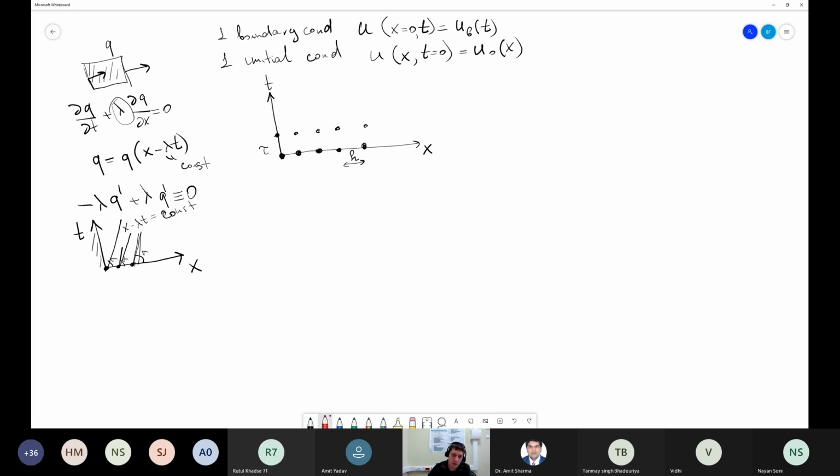The first try is to go from this point at the current level for the time tau along our characteristic, but the characteristic angle depends on the equation itself, while our grid node positions depend on other things, like how many nodes we can store in our computer, or how fast we have to simulate our problem. So we will obtain something like this.